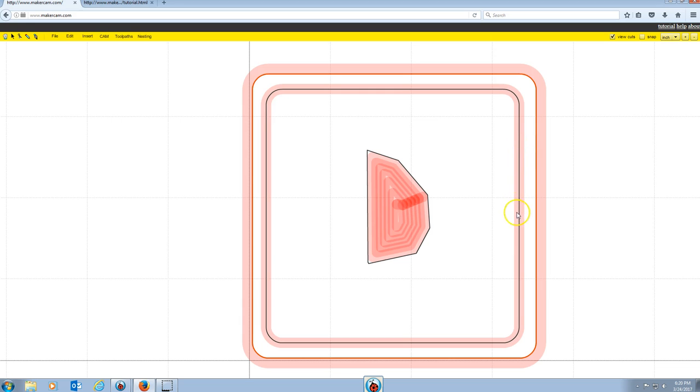So the center of the cutter is going to follow that line, and it's going to cut out an 1/8 inch wide area, 1/16 on either side. And then on the outside rectangle, as we work our way around this line or this rectangle, the cutter is actually going to be working on the outside and cutting through the material and leaving just what's inside that line.